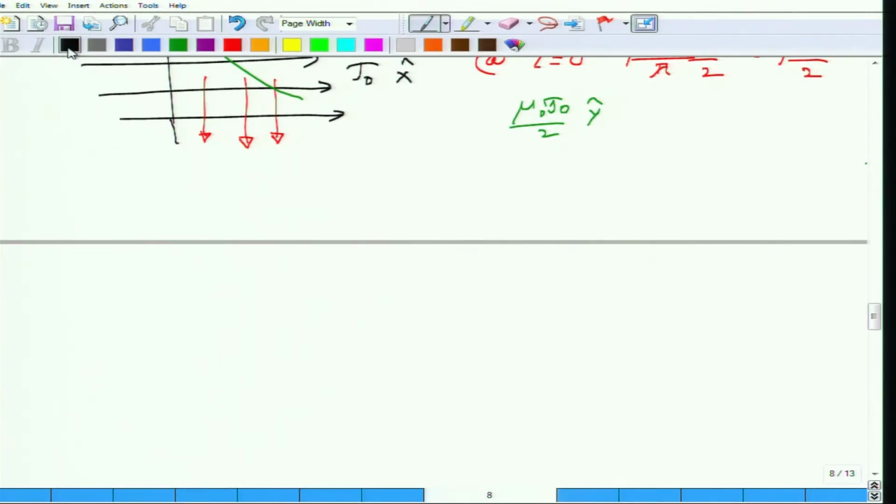And the reason to introduce this H field is this: we imagine that current actually generates the H field, and this H field is related to the B field via the material properties. As opposed to electronic properties or properties of the electrical materials, magnetic materials are much more exotic. They are highly nonlinear most of the time, and they also have some sort of a memory in between them. This is called hysteresis. You must have heard about hysteresis.